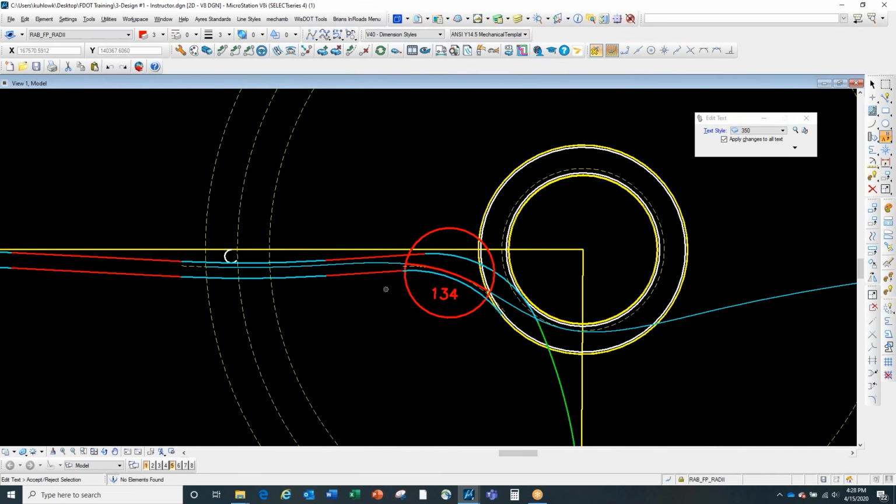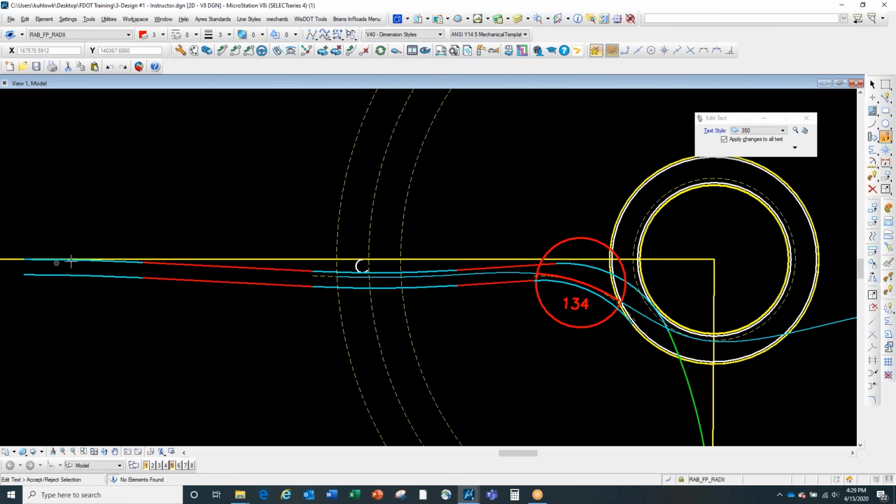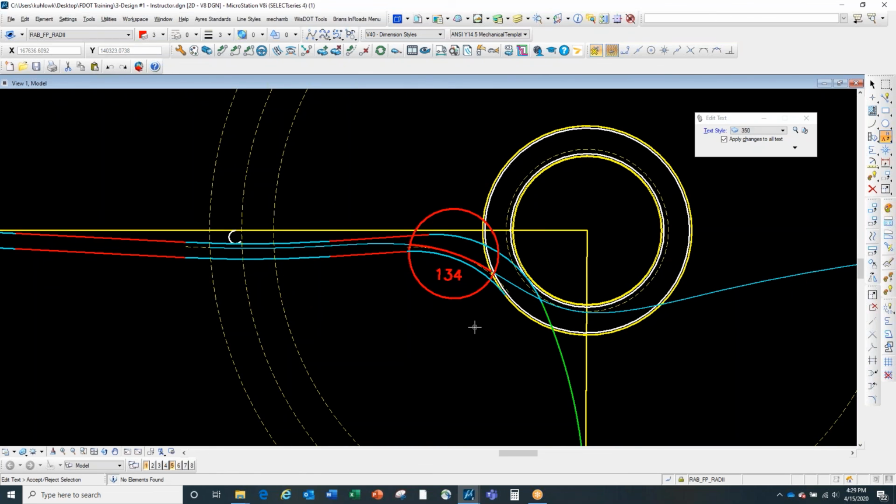So there's a quick example walkthrough of the iterative process of designing a single lane entry based on the Florida Department of Transportation's FDM, that exhibit that's shown in there for high-speed approach. We have a splitter island that's 200 feet back. We're using the appropriate radiuses depending on the approach speed. We've provided the tangents that they're looking for, the minimums, if not a little bit more. We are providing an appropriate fastest path, and we're accommodating the design vehicle.